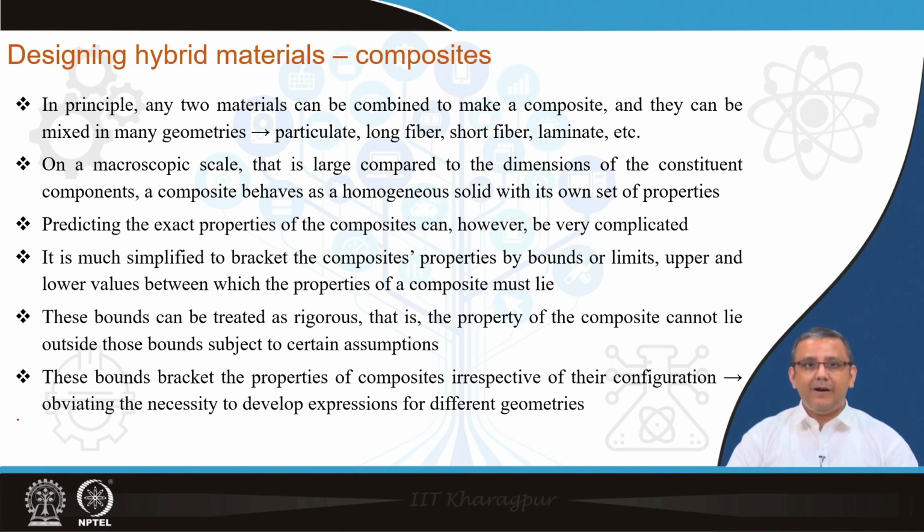Now, what is the function of these bounds? As I already mentioned, these bounds serve to provide brackets within which the composite properties will lie. That means, using these bounds one will not get the exact material properties, but knowing the composite material's constituent volume fractions, particle distributions and particle shape, one can predict the approximate value of the composite's properties. And for many design applications, this is a very efficient way, because it is cost effective, simple, and the bounds are well established.